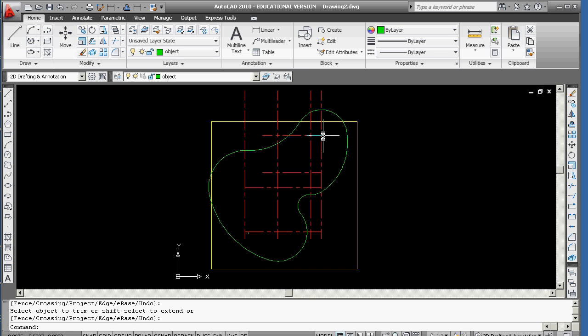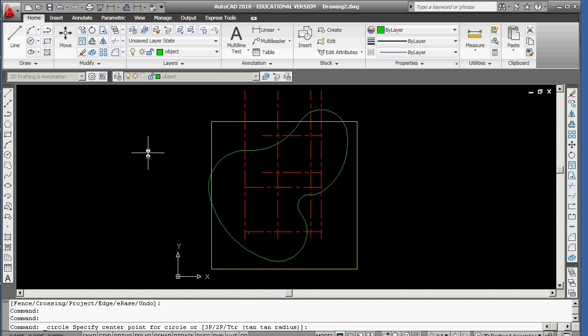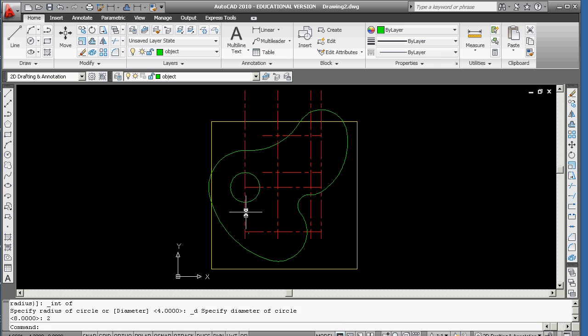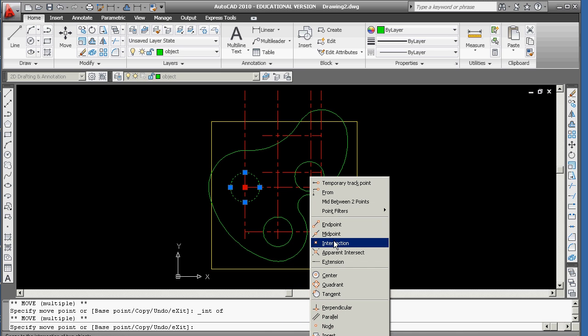All you've got to do is put back your holes, if you would. And you can do that by offset or fillet. These are radius of 3 at phi of 2. So I'm going to go circle diameter from the intersection there with a diameter of 2. Now you can start to learn. I left click, spacebar, move. I'm going to move, I'm going to copy, and then copy to, shift right click the intersection there, shift right click the intersection here,